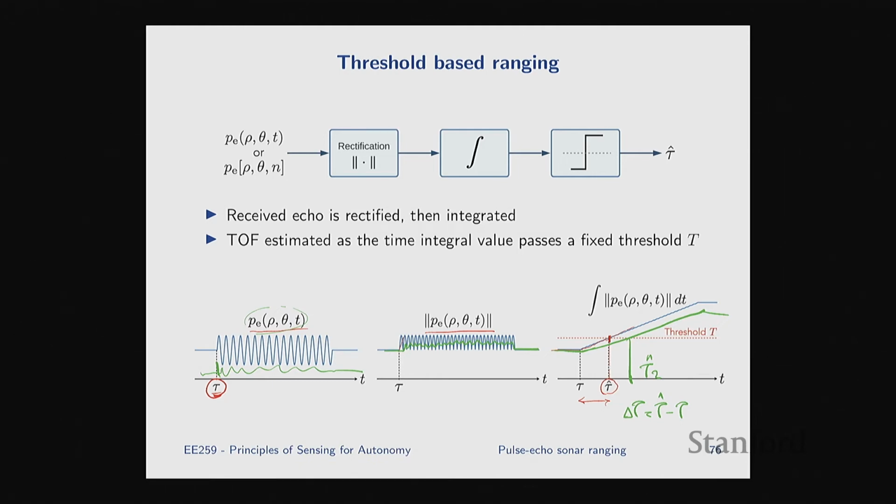The second case is if the targets are at different ranges. Then the echoes are going to get to you at different times. So you receive the first target, and then a bit of time goes by, and then you receive another echo. This you can detect, and that's actually what good receivers do: at the output of this integrator, as soon as it crosses a threshold, which we call a target detection, they reset the integrator.